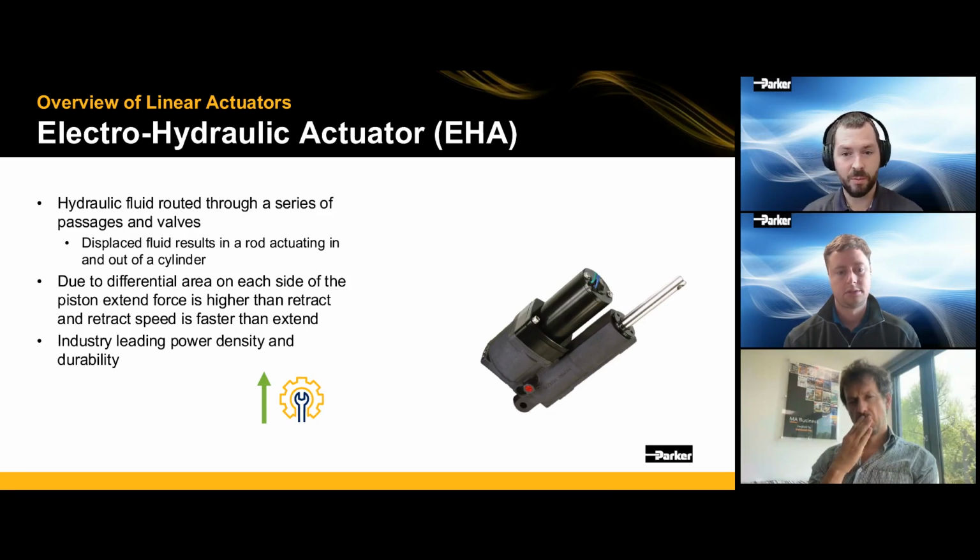These are very robust and have industry-leading power density due to that hydraulic nature. And if you have a harsh shock or vibration application, maybe you're on a ground engaging scraper or something, and you hit an object like a rock, these actuators are really good at absorbing that shock load and relieving, where a mechanical system is more likely to have a really abrupt failure, like bending or breaking some component.